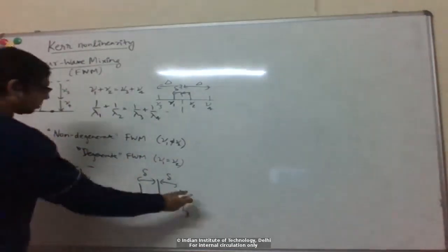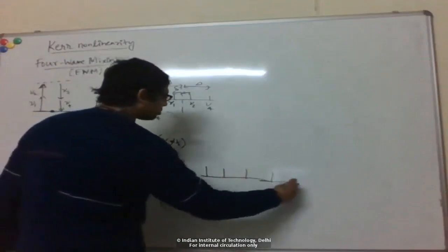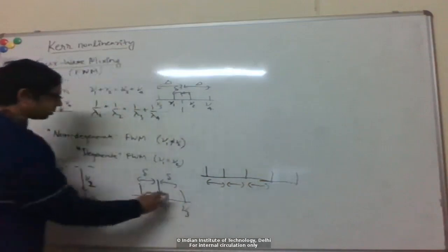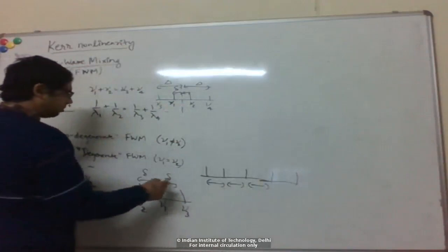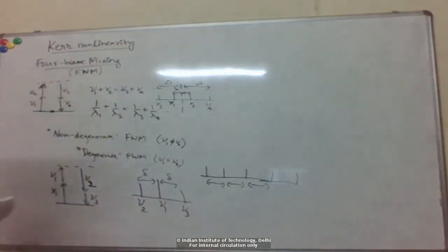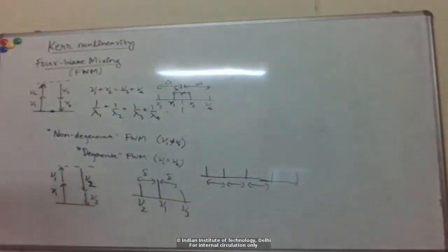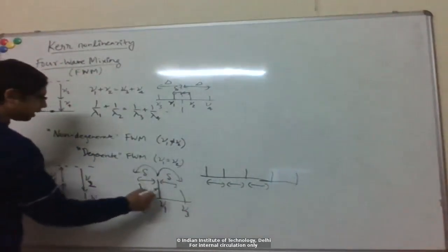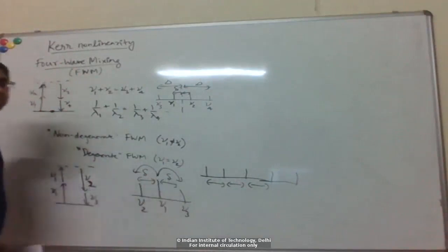And of course, this is the case when, for example, you have a WDM grid, where we are sending a grid of wavelengths, and typically they are all equally spaced in frequency. So again, for the DWDM grid, we have delta equal to 100 gigahertz, right? So typically we have this case when we are sending multiple channels. So in this case, energy can be transferred from nu1 to nu2 and nu3 due to this process.